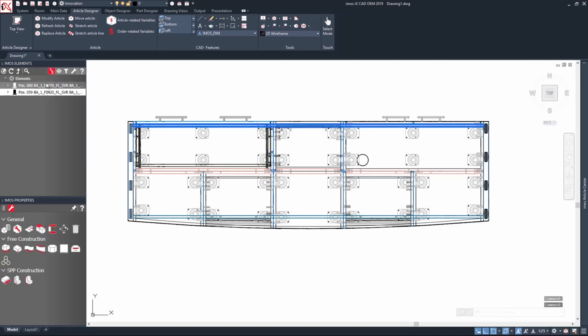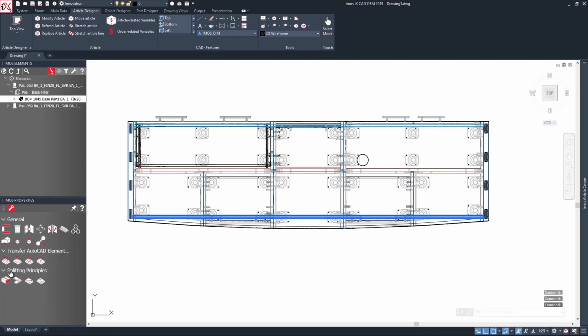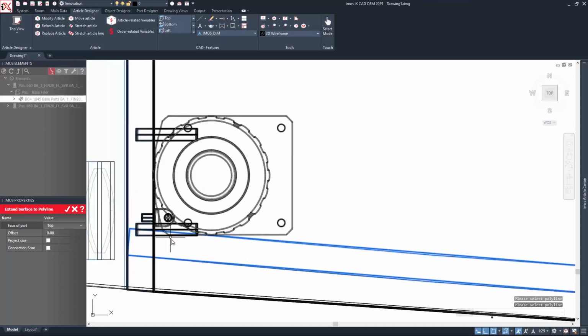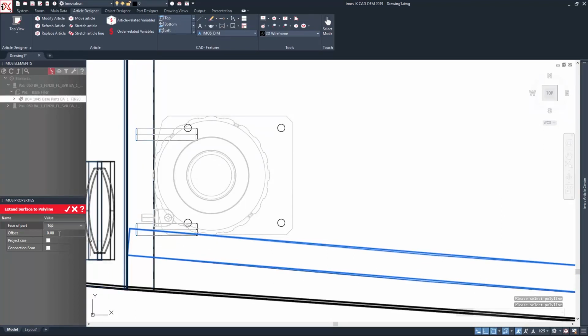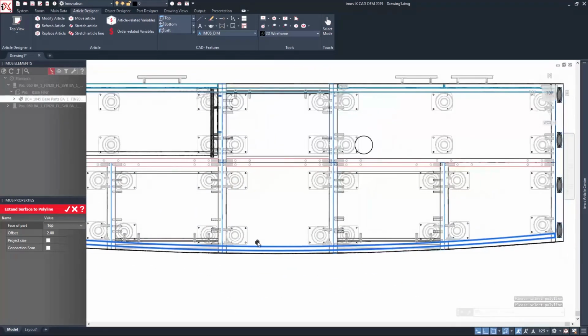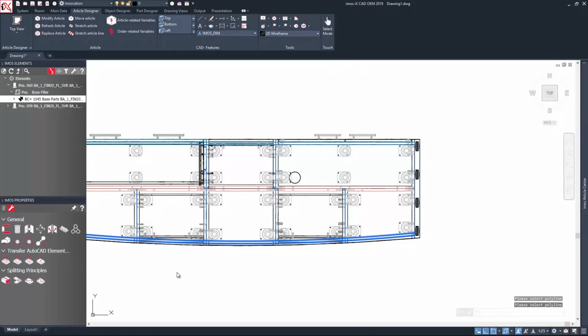That's better. What I'll do is open up my plinth here, and then say that I want this part to bend or extend the surface to the polyline that I've drawn. So I'll change that one, and you can see it's now bent my plinth and given me an offset. I'll zero that offset because I want that to come in here, and I might just give myself a 2mm tolerance. This looks better, it's not hitting anywhere along. And then I'll click tick.